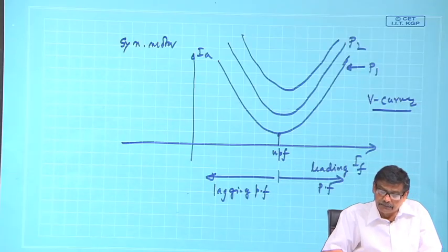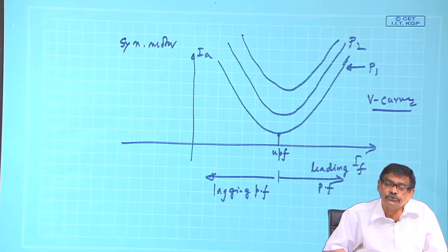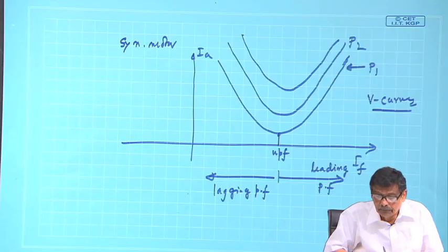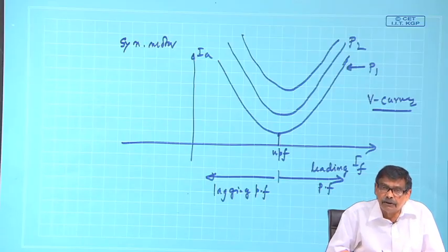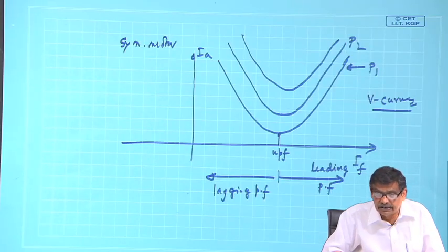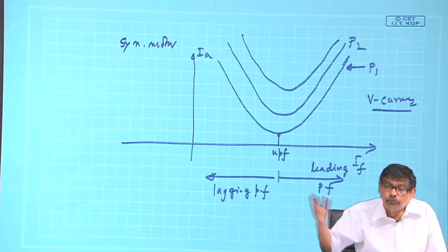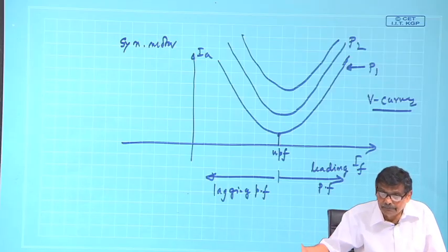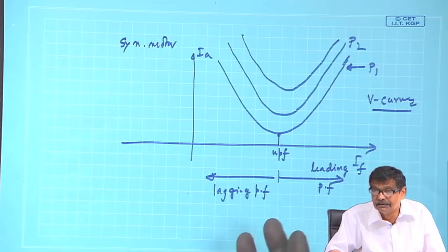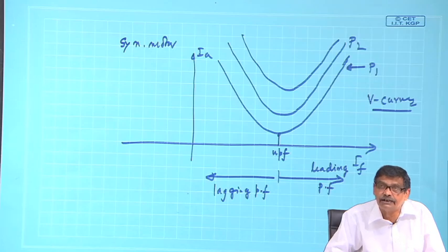So, what is a V curve? V curve is nothing but it shows that when the motor operates at constant power, that is shaft power I will not touch, then be it in case of generator, steam input I will keep the same, then output power has to be also same, because I have assumed machine is as if lossless, there is no R_a.